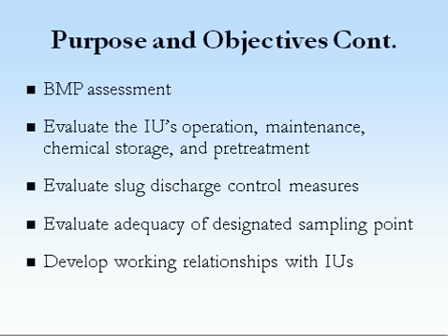Additional activities for which on-site observations are paramount include industrial user implementation of best management practices, including checking to see if they are properly documenting those activities that they are required to do in their records, and reviewing chemical storage areas, noting chemicals stored that might impact the POTW, as well as the proximity of the chemicals to floor drains, and the integrity of the storage area, such as strength of the containment berms and size of containment area, to ensure that an accidental release would not result in a harmful slug loading to the treatment plant.